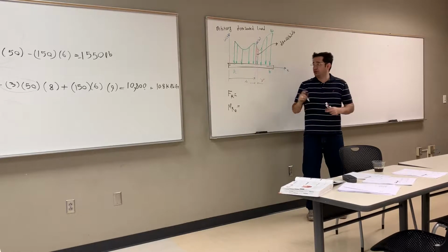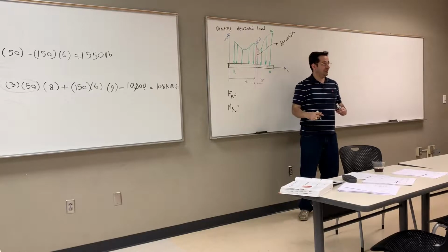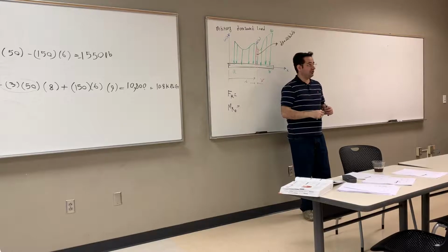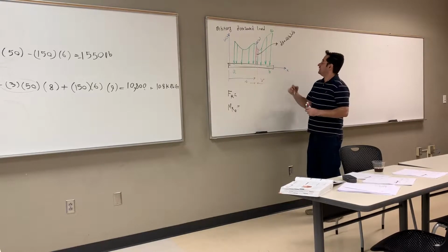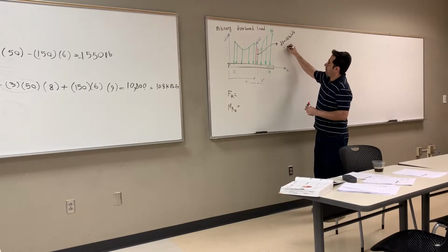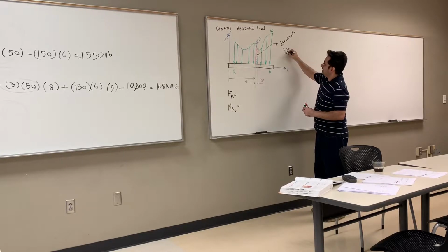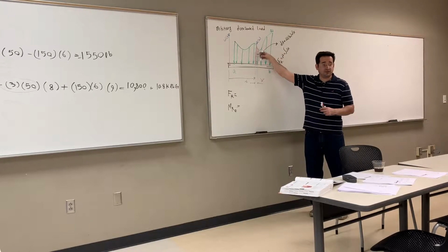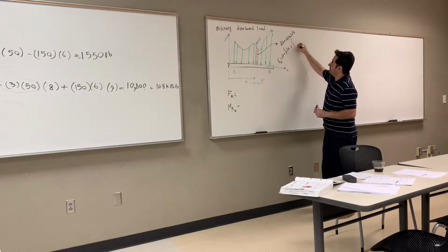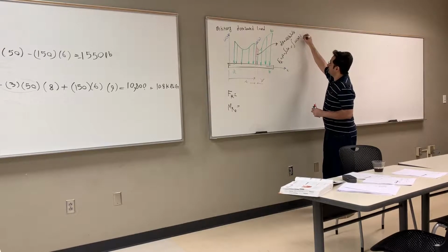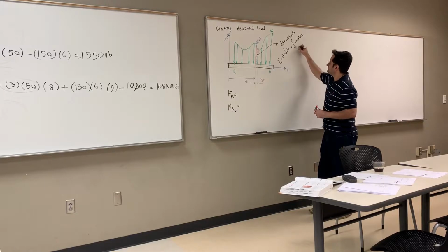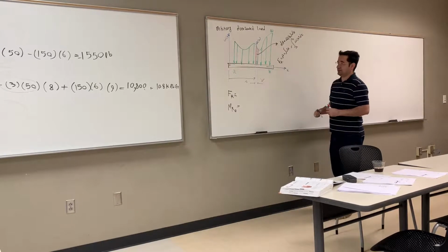So what should I do in order to find the resultant? Add them up. And in the limit, because they are infinite, I do an integral, right? So the integral of all dA is A, or the resultant force, because each one of those was a single tiny force, right? Which is equal to the integral of omega x dx from where to where? From A to B, right?